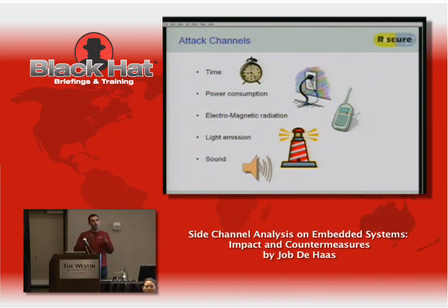a code that's compared byte by byte, but the compare function quits after the first non-equal byte. So by looking at the timing, you'll see differences if 3 bytes are equal and then there's a mistake, or if 5 bytes are equal. It takes a little bit longer for the compare function to terminate, and from that timing difference, you can have kind of a brute force attack on each byte, only 256 checks, and then you'll see a timing difference for 1 byte. You know that's the correct one, and so you walk the whole 8 bytes or 16, whatever the length. Power consumption, electromagnetic radiation, we'll show you a little bit later.